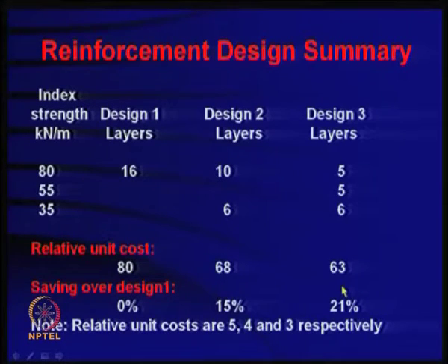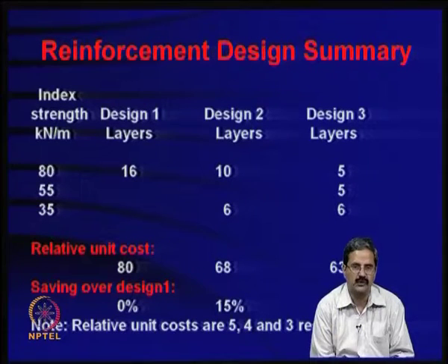Even within that geosynthetic material, normally see what you did, 8 meters is definitely unstable, you do not get any factor of safety, it is definitely less than 1, and you use geogrid reinforcement, and actually these reinforcement charts that I just showed you are based on a design coefficient of 0.8.